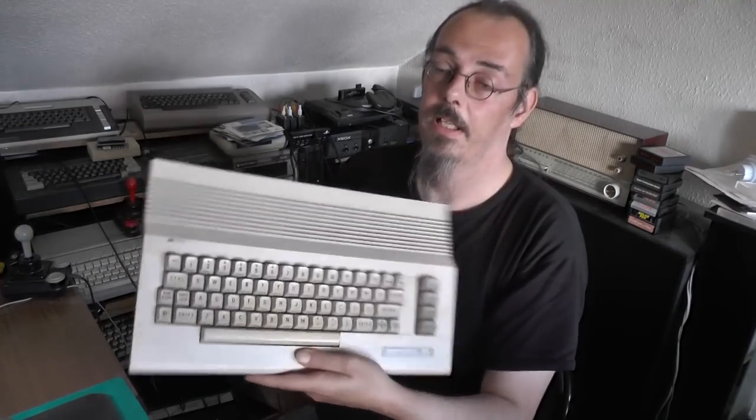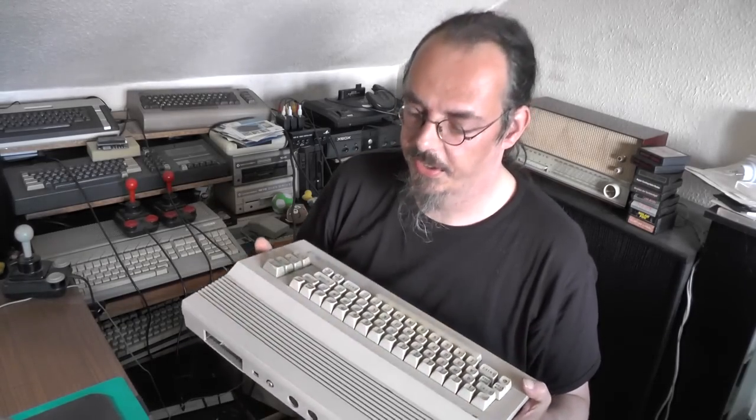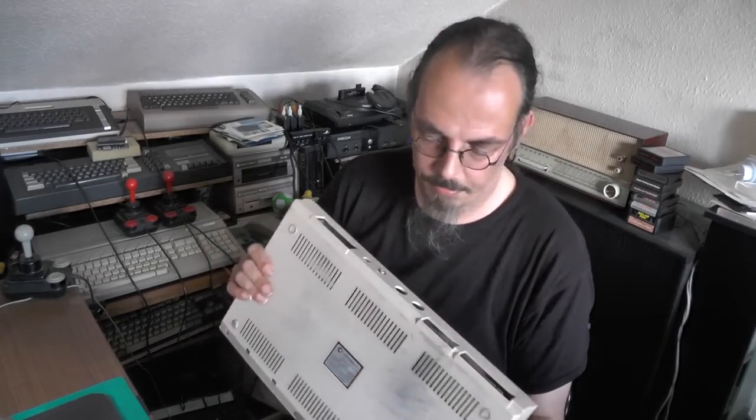This one. It has a 6510 CPU, which is a 6502 with some registers to handle the memory mapping. 64K of memory. The famous VIC-II video chip, which does smooth, soft scrolling in any direction, horizontally, vertically, and only 16 colors, but not too bad. 8 sprites. Technically 8 sprites per scan line, because it can handle raster interrupts and you can easily have more than 8 sprites.